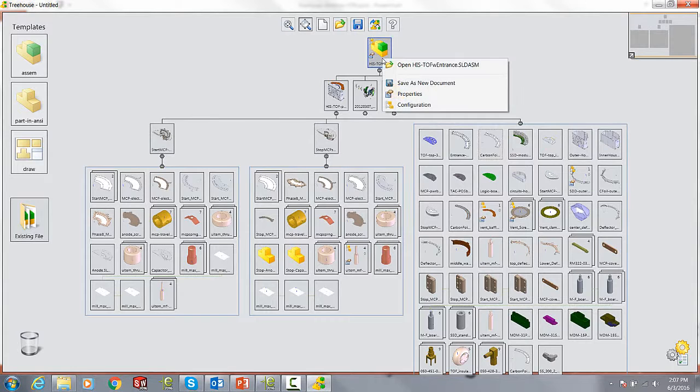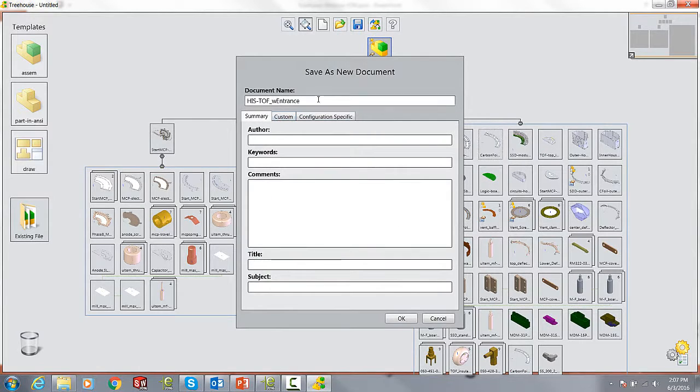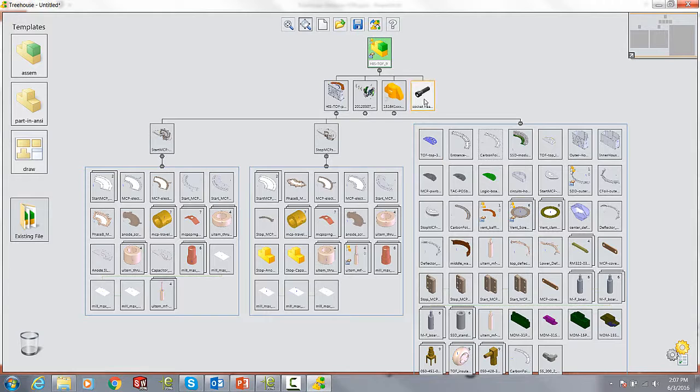Now the next step at this point is to generate a new version of this. So we're going to give it a new one, version 9 in my case, and yes, there are 8 previous versions. And notice the icon goes green. So if I save this structure out, it's going to be a new assembly structure, and I can export that new structure all the way out to SolidWorks and have it reopen with new items. I can also drag and drop new parts using templates of my own and start building up new components.